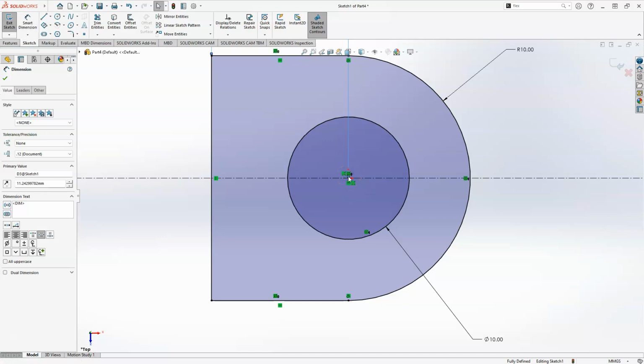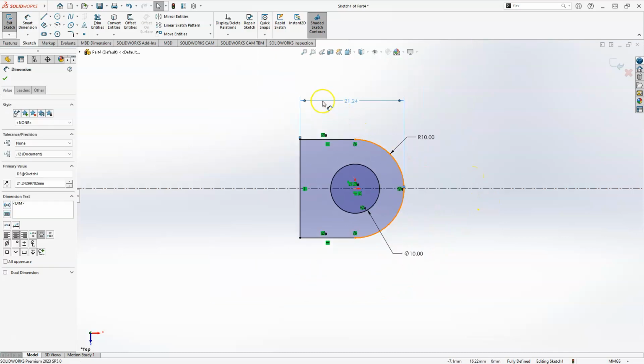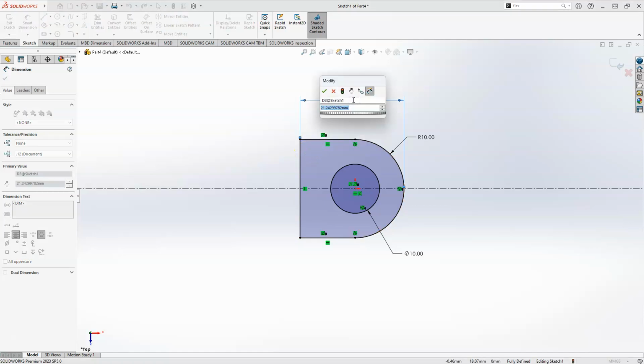You click on it, single click, and then come all the way to this point, and that gives you a yellow rectangle. You select on it. Now your measurement is truly from the very end point of the arc all the way to this line. So this is 20.